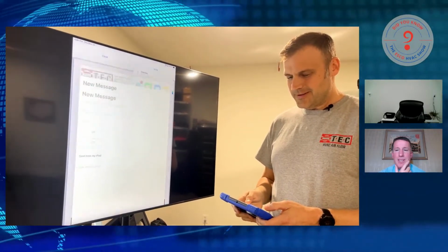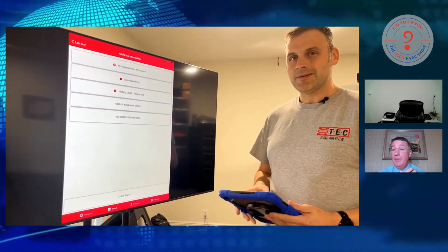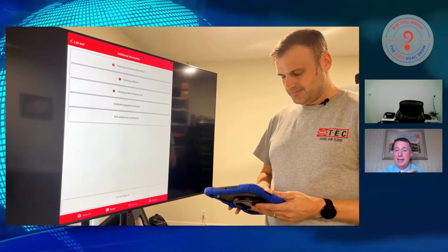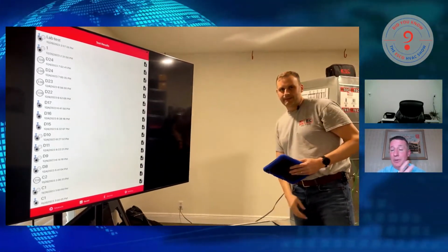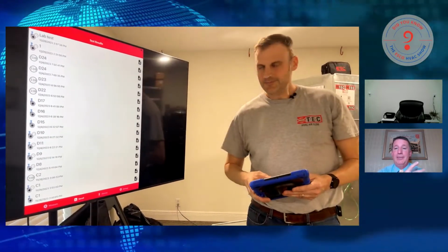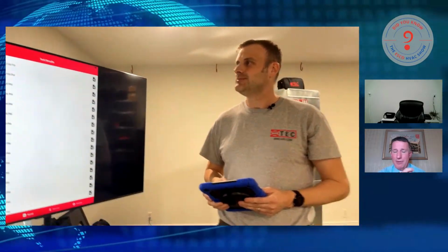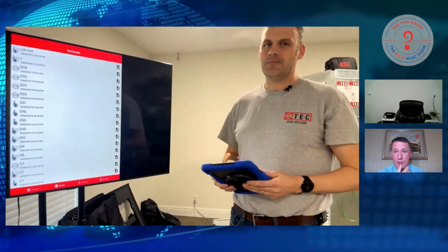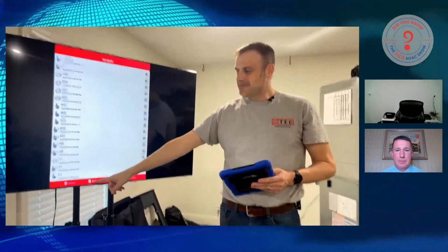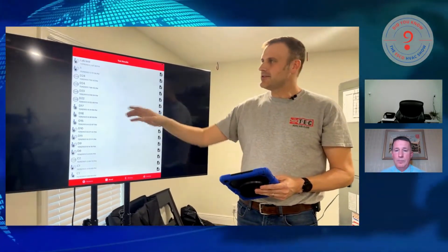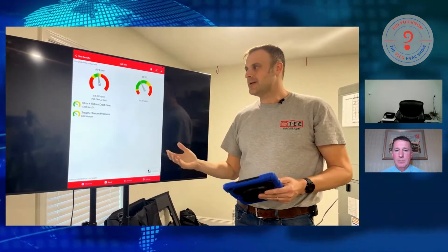Yep. I mean, think about that job where you're going out to evaluate it, a call, hey, I have poor airflow. And even if it's just a coil cleaning and a technician does a 5-minute pre-test, get an idea what's going on, do a complete system clean check, clean coil, validate it with a second follow-up, you're showing how much of an improvement you have on the performance of that system and the airflow moving through that duct. Yep. All right. And so I just want to point out down here in the save button, right? This is where your tests are going to, when we saved it earlier during the workflow, they land here. So we can pull that test back up at any time we want.